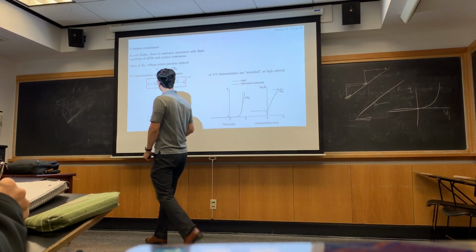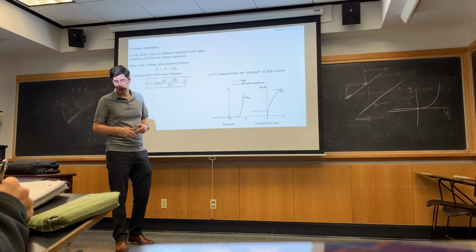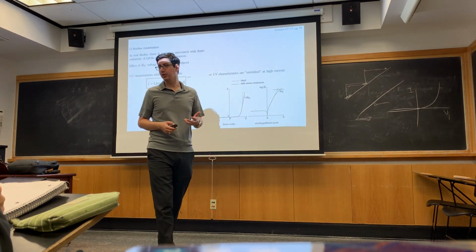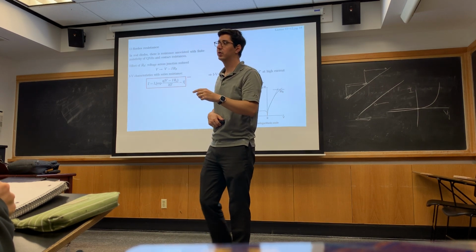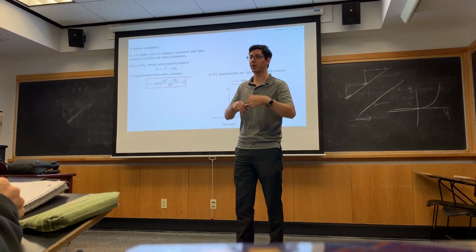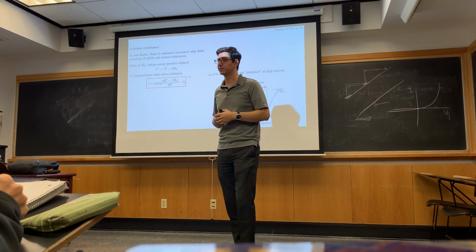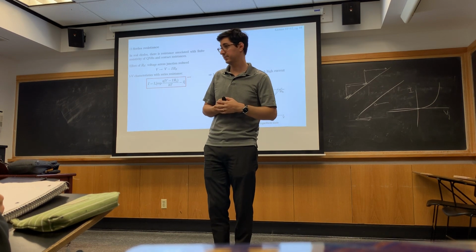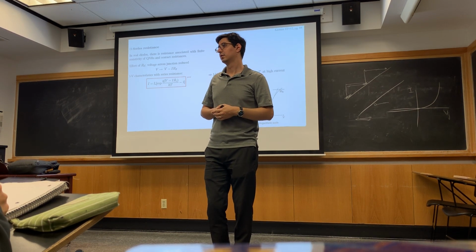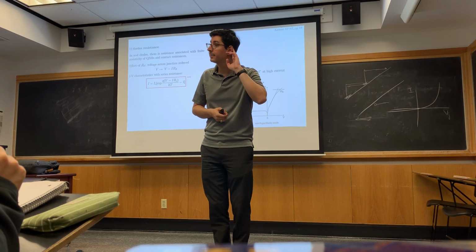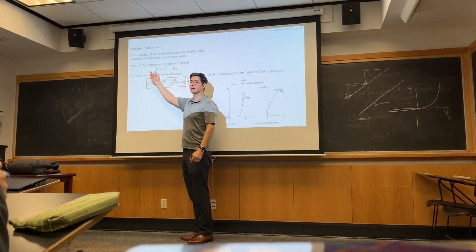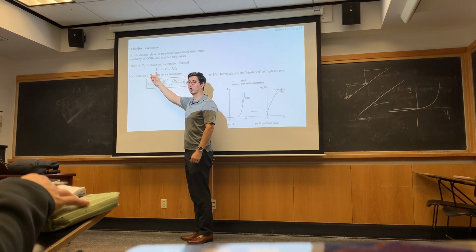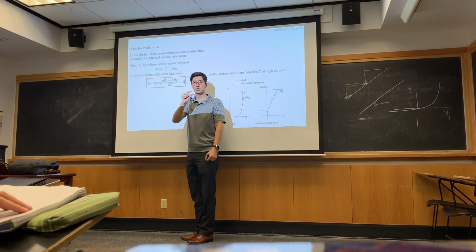And so what that means is, if my diode is conducting some current I, what is the voltage drop across all those series resistors if their series resistance is RS? IRS, right? So if I apply some V, before we assumed that all of the V appears across the junction.